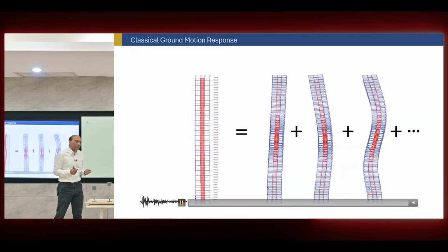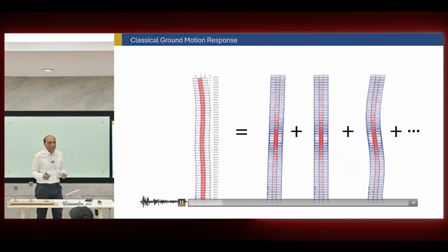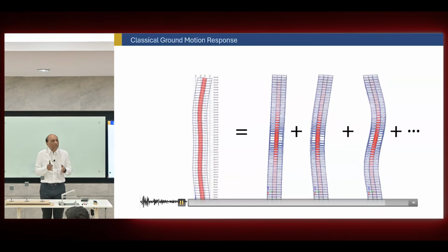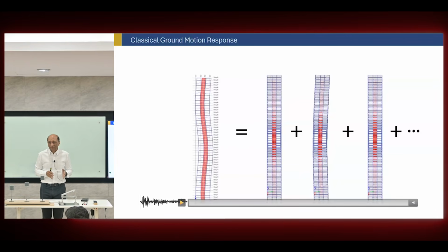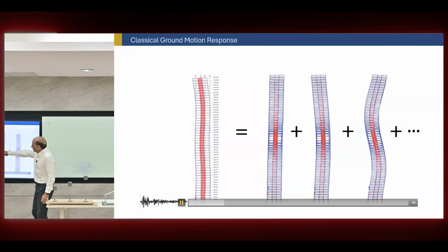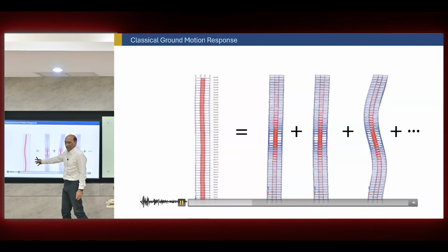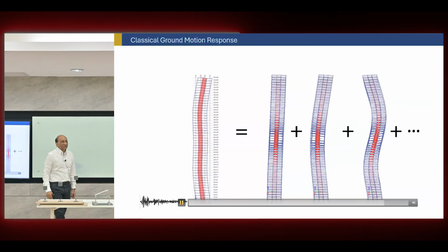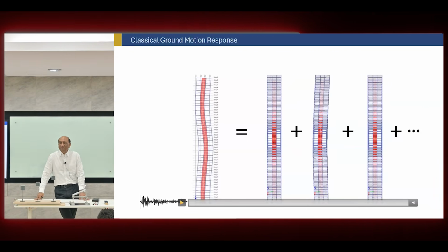That means for a ground motion, because it has so many modes, the final shape of the movement will be a summation of the modes that will be activated. So that means the structure's final response is not one mode, it's a combination of modes. And that will bring us to modal combination later when we discuss. So you can see, watch, this building is moving randomly, appears to be moving randomly, but it is nothing more than the summation of its natural modes in different order, different factors.